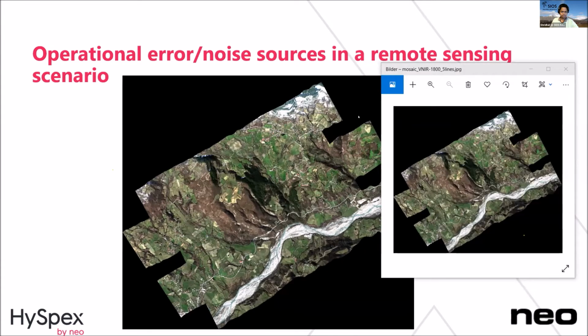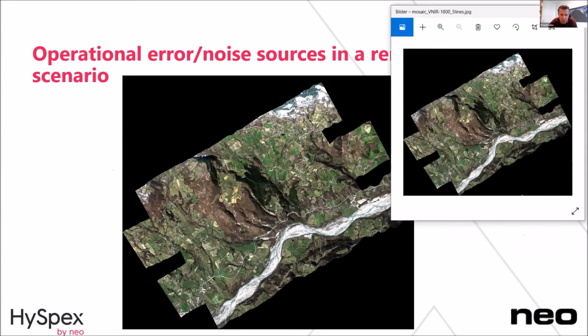So I will now talk about the operational sources of errors you can have. I just wanted to show an example of an auto-rectified image from the same model of system as Agnar has in the SIOS aircraft, or the NORCE aircraft. The 5 flight lines here were done in Italy, in Parma. In this flight there is 900 meters difference in ground elevation. We are flying LiDAR together with the hyperspectral sensors. This is also together with SWIR, so it's a merged cube with NIR and SWIR.